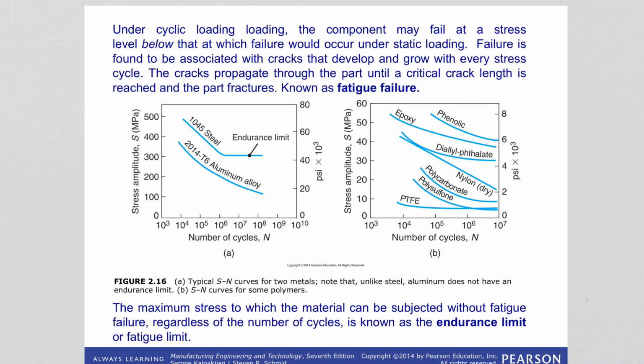So what is fatigue? Many components in manufacturing, the tools, die, shafts, are subjected to cycling loads. What is cycling load? Like the part will be under tension, compression, loading cycles. And under these conditions, material usually fail, even if the stresses that it is exposed to is lower